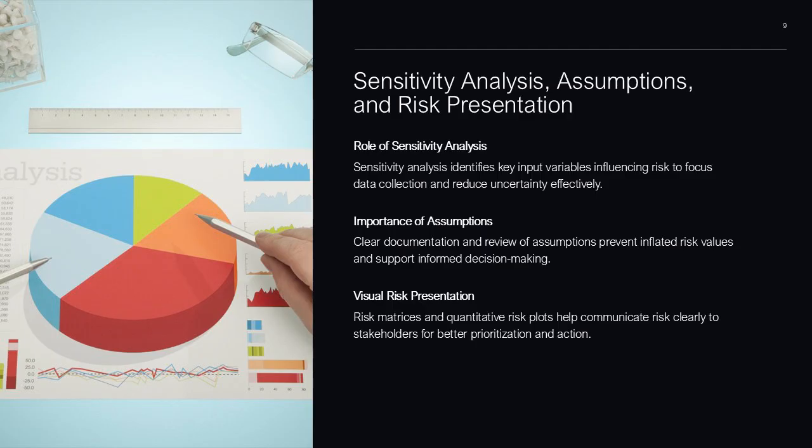Risk matrices are commonly used in qualitative and semi-quantitative assessments to visually communicate relative risk using categorized probability and consequence scales. They allow stakeholders to quickly identify high-risk areas without focusing on numerical detail. For quantitative assessments, risk plots provide a more precise view, often using logarithmic scales and displaying risk thresholds or ISO risk lines. Both tools support prioritization, screening, and communication, ensuring that technical results are understandable and actionable for decision-makers at all levels of the organization.